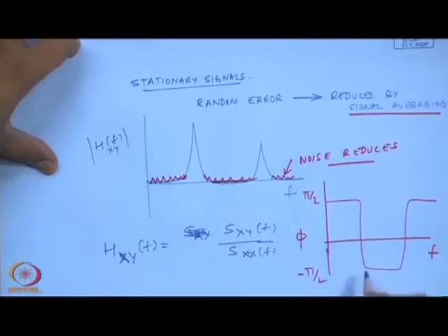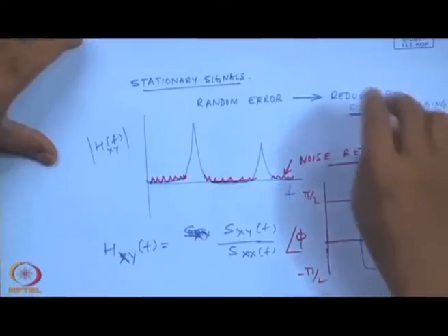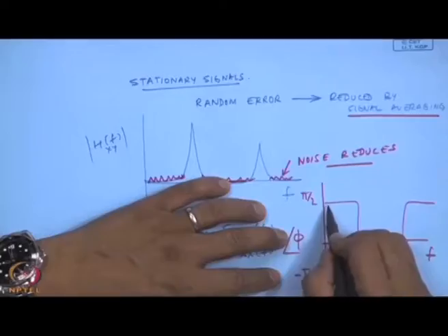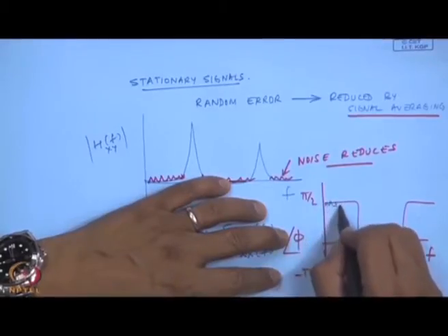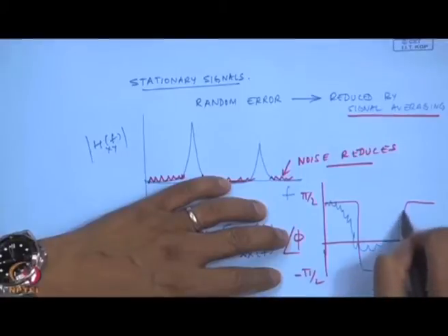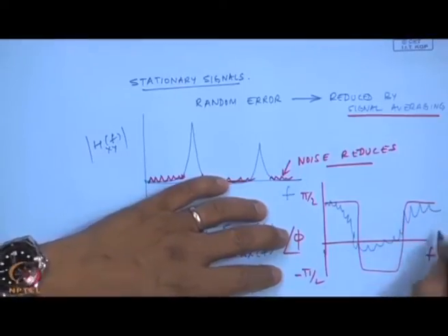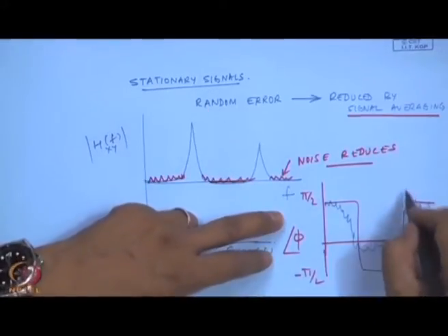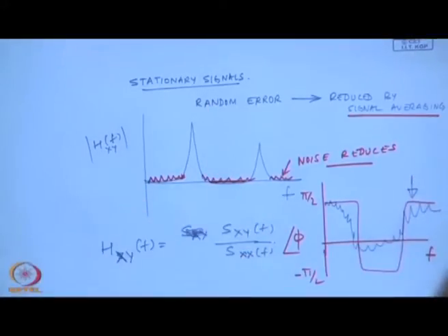Phase of the transfer function. However, when you do such analysis between two signals coming from a machine where there is a lot of looseness, you will see that this phase will make no sense, because if you do an average signal, you will not get any meaningful information. That is what I mean by unstable phase between signals. These are clear indications that a system has looseness.